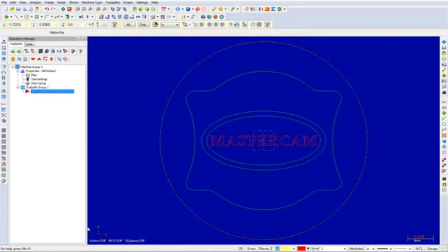In this video, I will cover a 2D high-speed core mill toolpath. A 2D high-speed core mill generates the free-flowing motion needed to machine features, such as standing bosses and cores in a single operation. Core mill requires two chains, an outside chain defining the stock boundary, allowing the toolpath to move freely outside of this area.